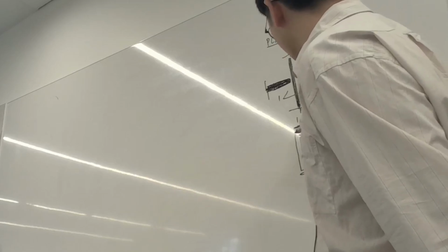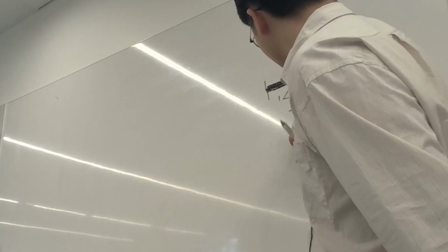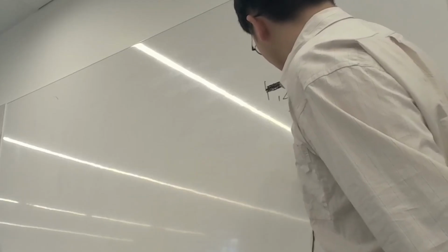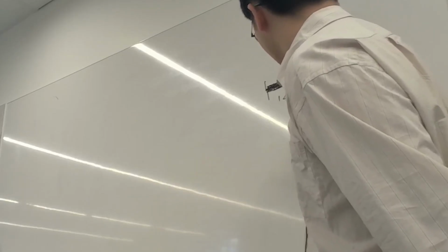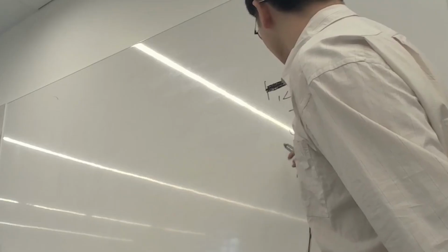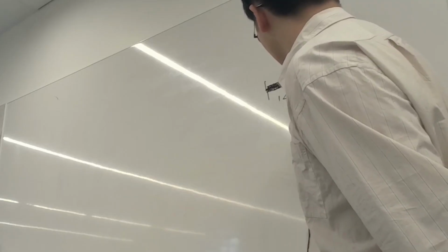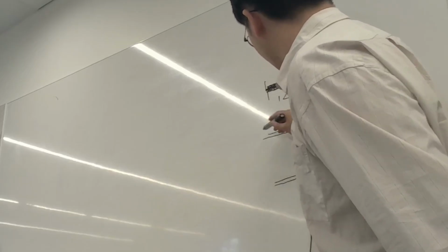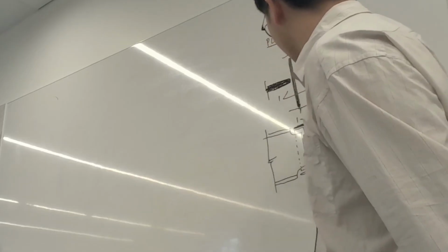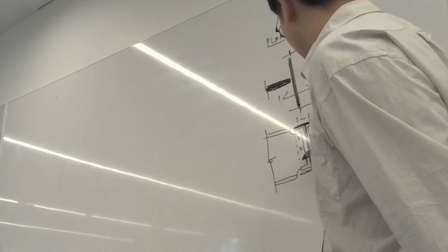And then what you might do is, sorry, not taper, you can cope the flanges of your secondary beam, like that, right? So that's your secondary beam coming off, and then you might add some bolts like this.